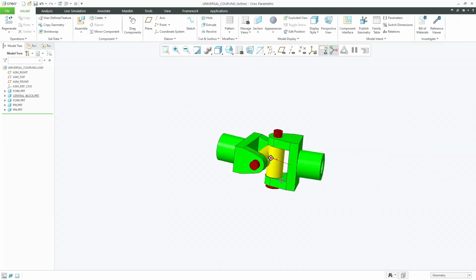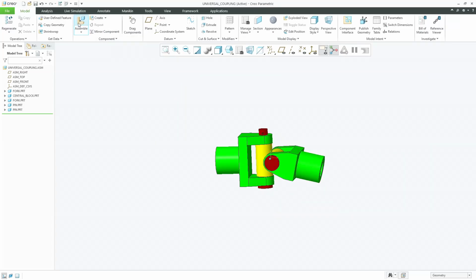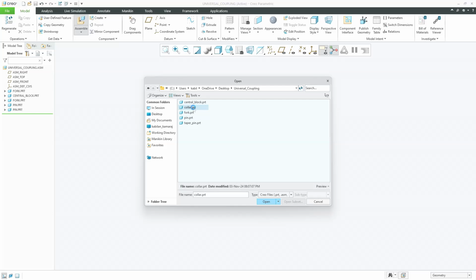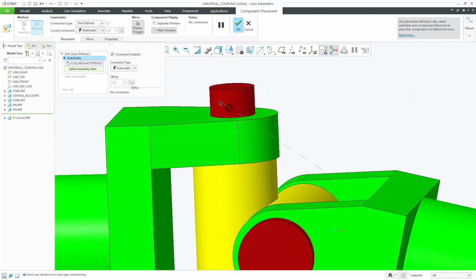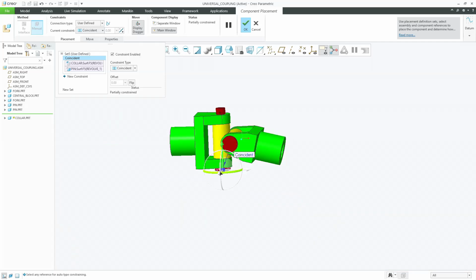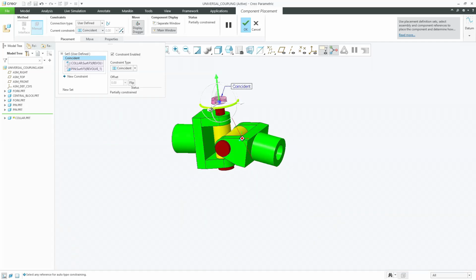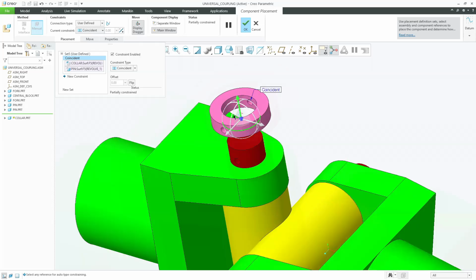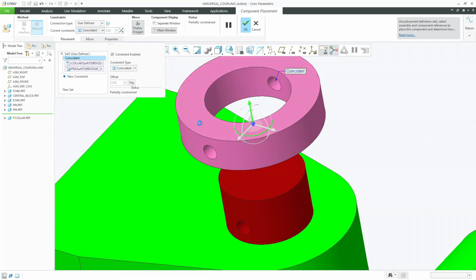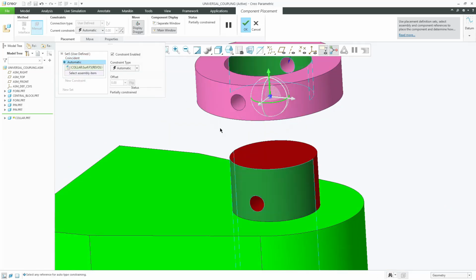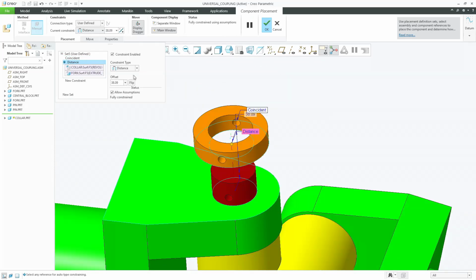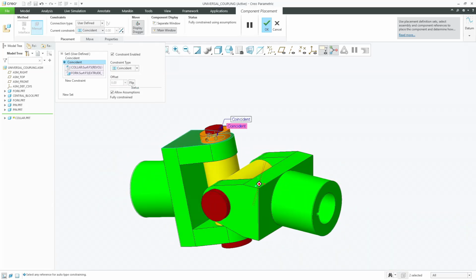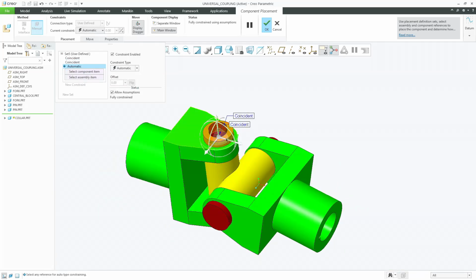The fourth part we are going to constrain is the collar, also having two quantities as per the bill of materials. It constrains both surfaces, so hole to shaft has a constraint, and the second one is a coincidence between surface to surface. And we also need another coincidence, where one degree of freedom has not been arrested,